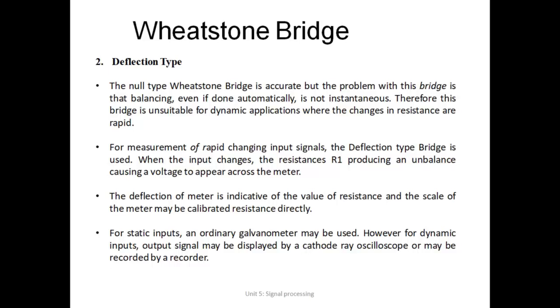Simply because of the current, there will be a deflection taking place, and we simply have to note down that deflection. And if you want to improve the circuit further, that deflection can be fed to a display device where you can establish a calibration between that voltage deflection or current deflection in terms of maybe pressure or temperature, whatever the physical quantity that you were measuring was.